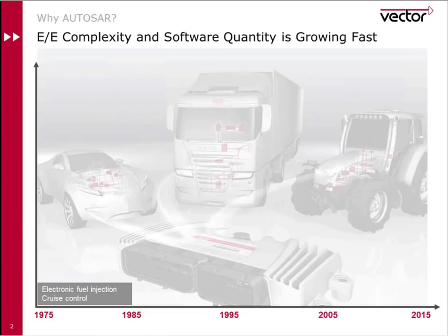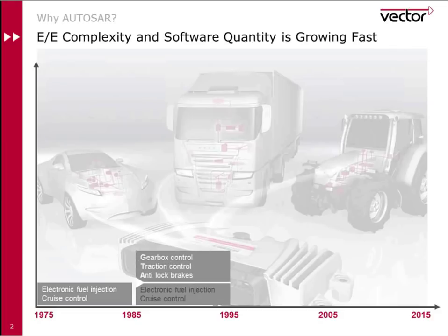Nowadays, the engine electronic control unit, the engine ECU, has more or less become mandatory in order to meet today's stringent emissions legislations. But along with the proliferation of the engine ECU, there have also been many other ECUs brought into the vehicle. For example, the transmission control unit for gearbox control, a braking ECU for ABS functionality or traction control. And these ECUs all talk over various network systems, and typically that communication might be something like CAN, Controller Area Network.